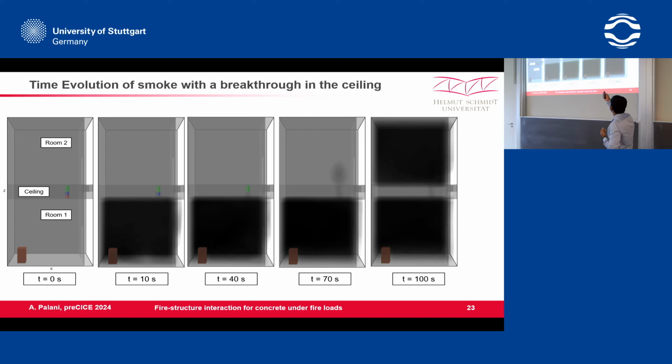Yes. This is a typical example for that. This may look like a single, simple hole, but before the simulation starts, it is completely solid, and the fluid solver doesn't know that it is a fluid domain. Once the hole starts to be created, and it is given fluid domain properties, it will start acting as a fluid domain. The best example is the propagation of smoke. Because it is a fluid domain, the smoke propagates to the next room, or else it would be stuck below the structure itself, even though I changed the geometry.